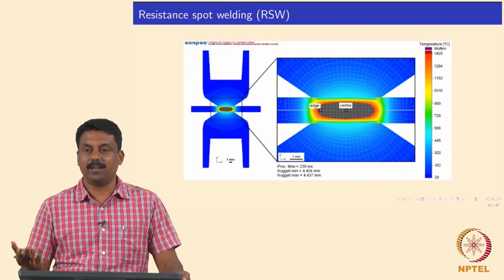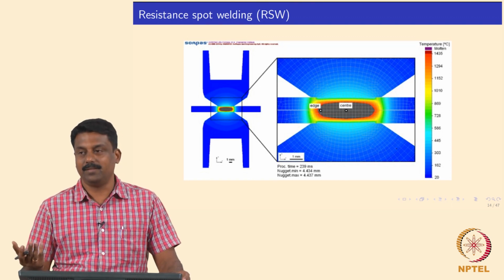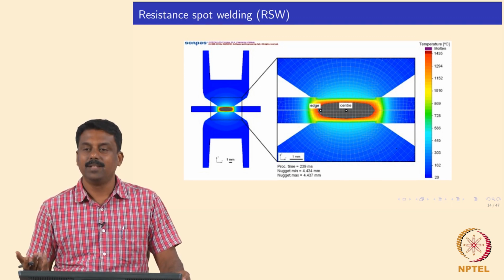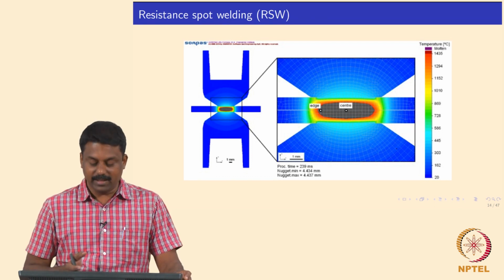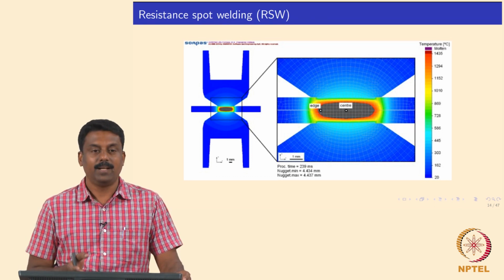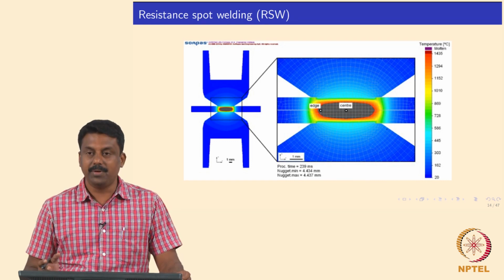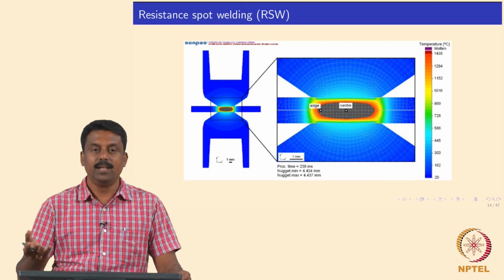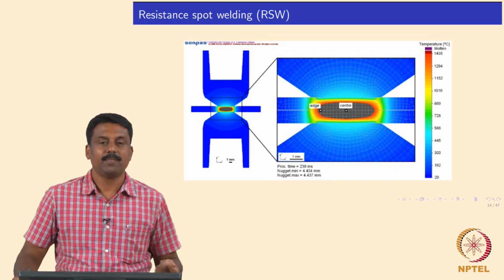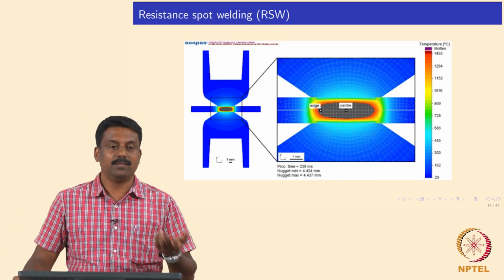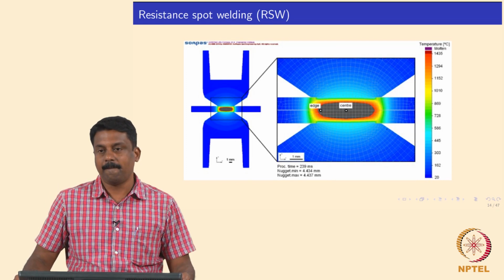Then we can solve for heat transfer, conduction, convection and radiation, and know exactly the temperature distribution in the weld nugget. So, we can get the exact temperature distribution from room temperature while applying whatever thermal cycle, the enhanced thermal cycle or the other thermal cycle.